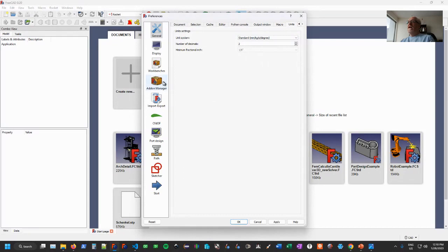In the add-on manager, actually, I'll come back to that later. Never mind. Okay. So one last thing about units is even with my units set to metric, I can still use imperial measures. So for example, if I entered 2.0 and a double quote, that'll take it as 2 inches, or 2.0 IN. Most of the fields will accept any standard supported measurement and use that accordingly. So it's good if you're, like I said, working metric in my case, but you have 1 or 2 imperial measurements that you need to